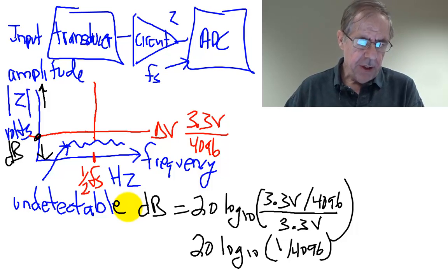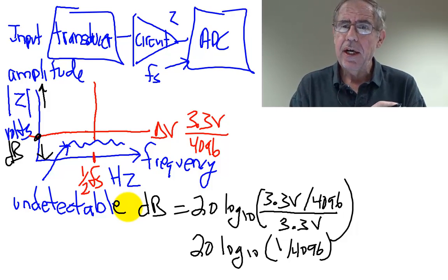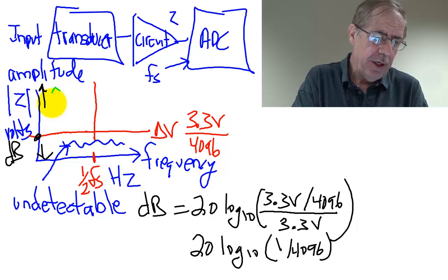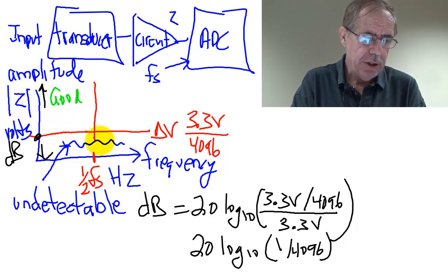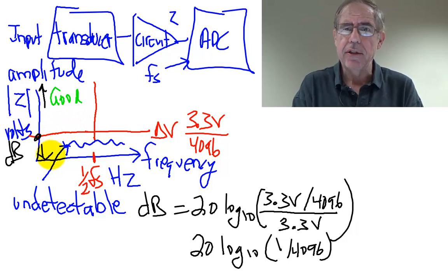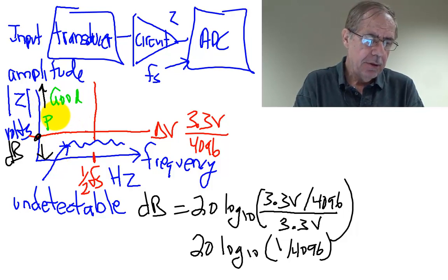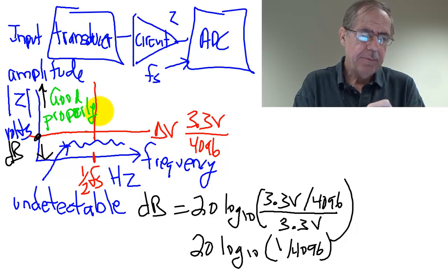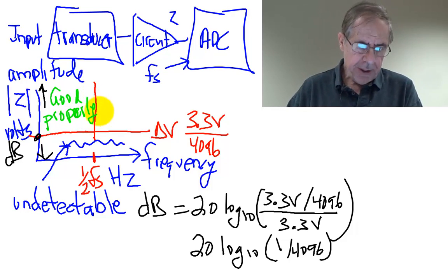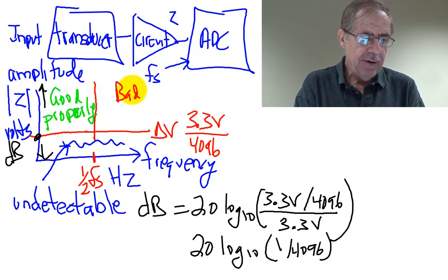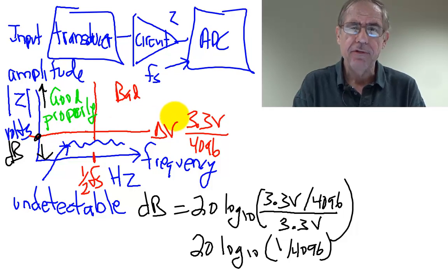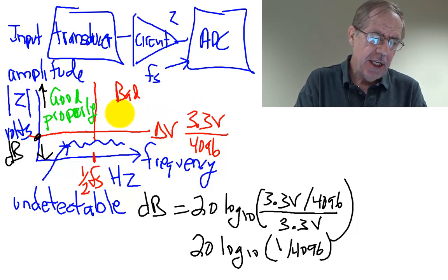But what I'm going to do is divide the other two into what I would say the good region here, okay, and this represents large amplitude, low frequency signals that are properly sampled. But the problem is this region over here, the bad region. What we have are large amplitude, large frequencies, and this is aliased.